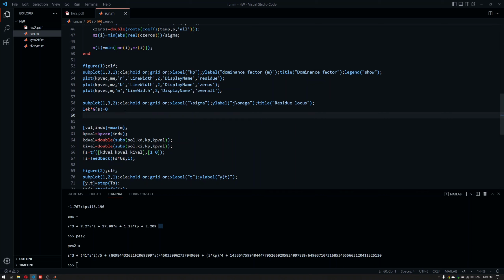And if you can convert any polynomial into this notation, where Gs is a transfer function and k is the unknown, then you can plot the root locus of Gs and it will correspond to the root locus of this polynomial, where you can determine the k interval, etc. Or observe the movement of the poles of this polynomial versus the change in k. So how can we do this? Well, I have to divide into a specific polynomial in order to get this notation here.